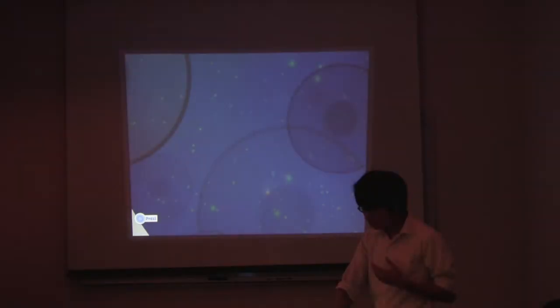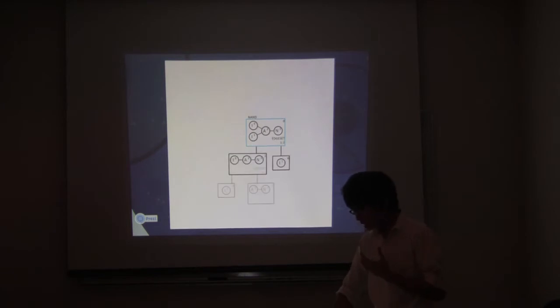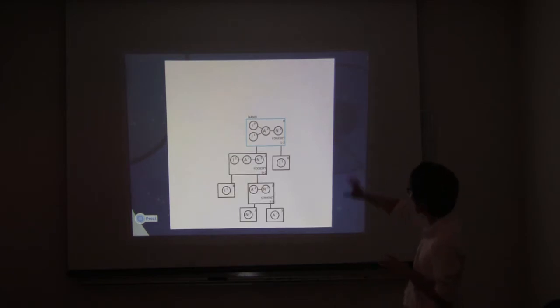So how the decomposer works is, given a circuit in the pattern database, for example, a NAND gate, we want to try and recursively decompose it such that everything is decomposed to a single vertex. So pretty much we partition the pattern into two graphs, and then once we do that, we partition the larger graph until it is a single vertex big. And as we partition them, we also keep track of an edge set. The edge set pretty much tells the relationship between the two partitions. So once we partition them, we keep track of the edges that we remove.